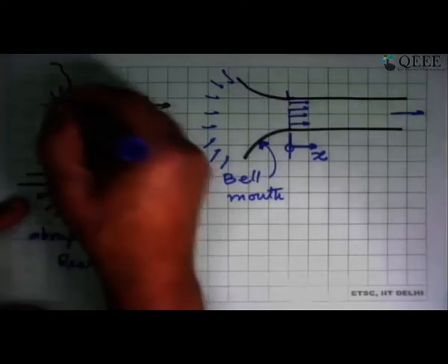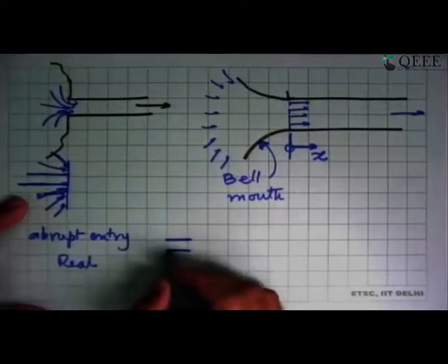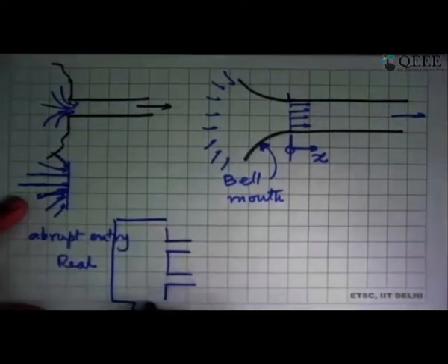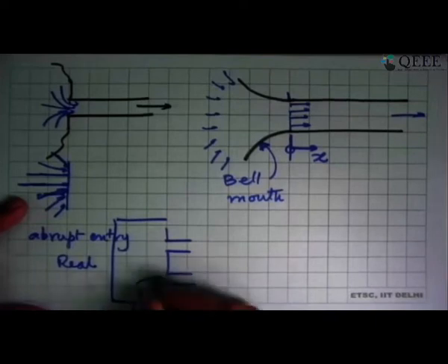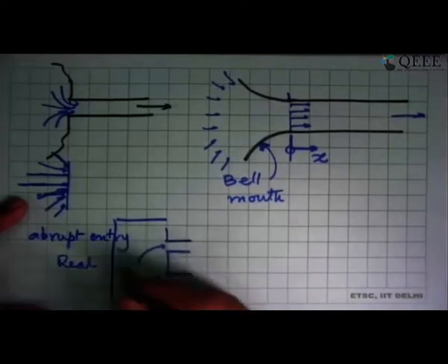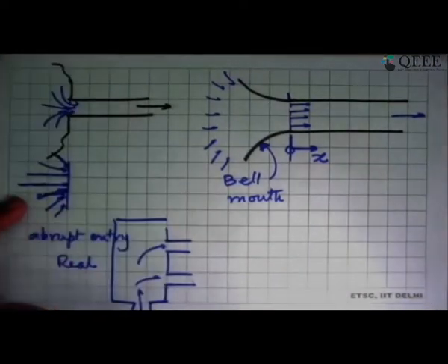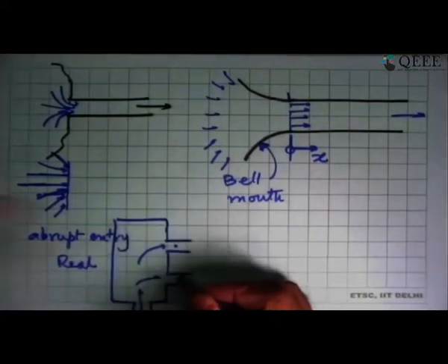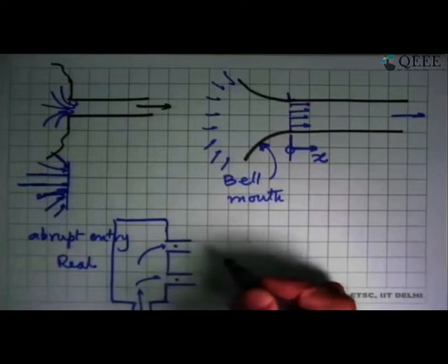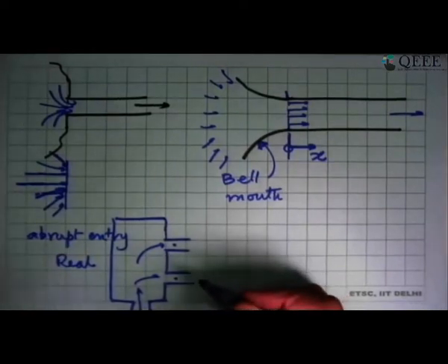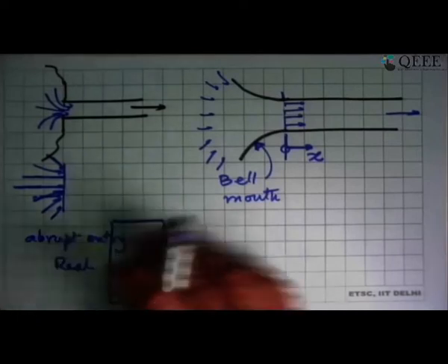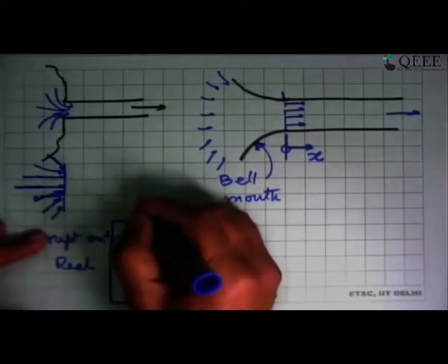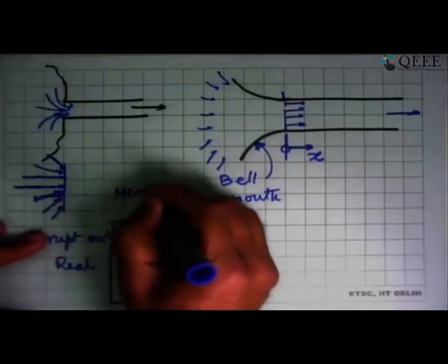It may not even be that symmetric, because if you have tubes over there, as you saw in that heat exchanger, and the fluid enters from this side, it comes in from here and is then distributed into the tubes. You would have even more asymmetry in the flow than what we have shown over here. Not to mention the fact that if this is not designed properly, there will be some tube where you have more flow taking place, some tube where there may be less flow taking place. So the assumption that all tubes have the same flow may not even be true. And that's what you have to worry about when you look at tube banks, and you have to design this and this particular shape that distributes this fluid into this. This in engineering terms is called a header.